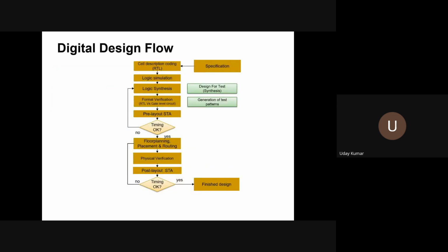So this is the flow of physical design. You do the synthesis, and once you convert it into gate level, you will have to retain the original functionality even when it is converted to gate level. That means you just converted a raw code that is almost equivalent to C, Verilog, to something else. You mapped it to Boolean algebra basically. The raw code, which is equivalent to C, which contains for loops and if loops and case statements, you mapped it to Boolean algebra.